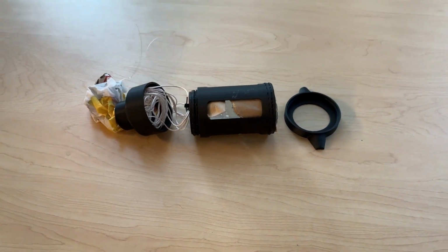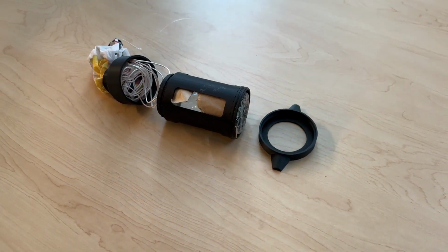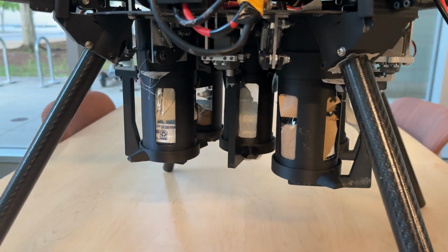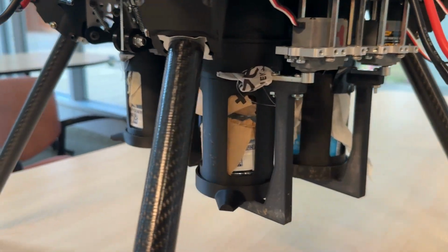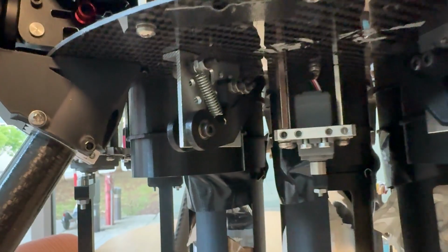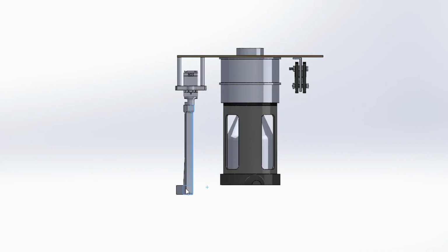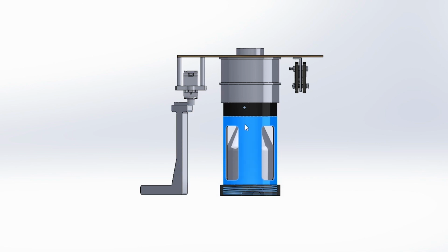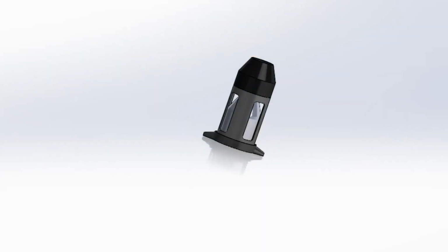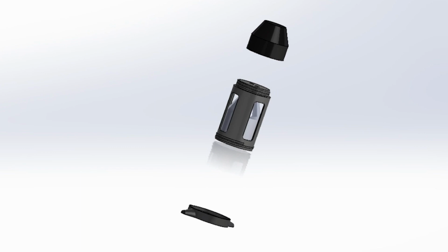The delayed parachute deployment system is a sensorless design. The parachute is initially packed tight into a capsule which also holds the bottle. A fishing line runs from the parachute to 2 spring-loaded lever arms. Excess fishing line is wrapped around a cylinder. The bottle then releases from the drone via a servo. The servo is actuated by the off-board computer once a corresponding ODLC target is found.